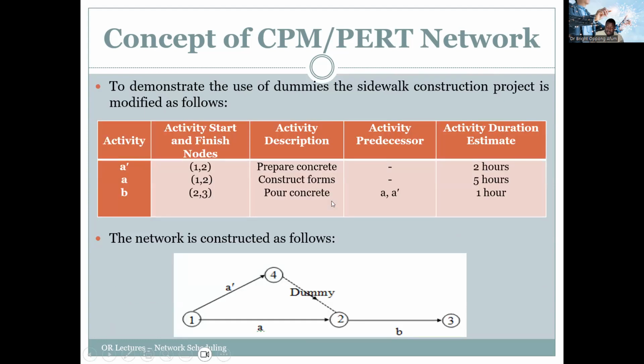So let's look at our form construction and the concrete pour, the University of Mines concrete walkway. To demonstrate the use of dummies, for the side walkway construction project, we can modify it and say that we need to prepare the concrete before we can construct the forms, and also we can pour the concrete thereafter. So you can see that the preparation of the concrete and the construction of the form can all happen at the same time.